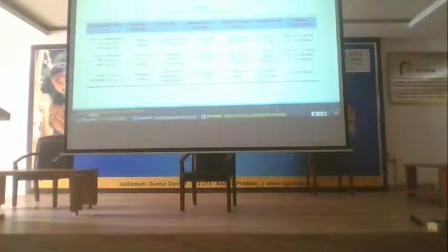Here you see the power ratings starting from 4 to 19.2 kilowatt, like 17 amps to 80. Whereas in single phase onboard, level 1 is up to 1.9 kilowatt, up to 20 ampere.